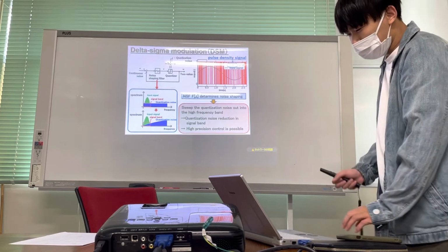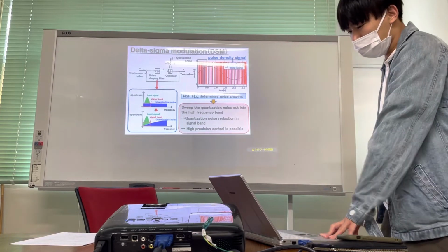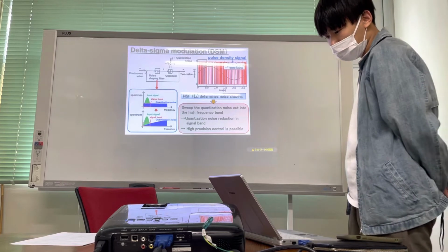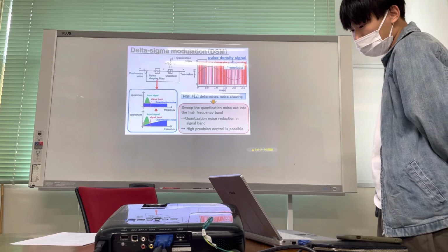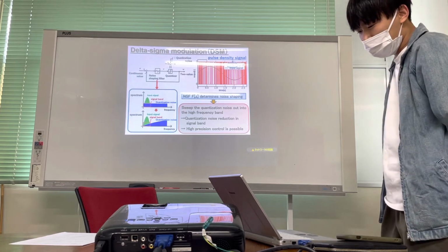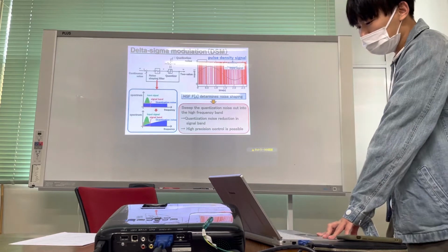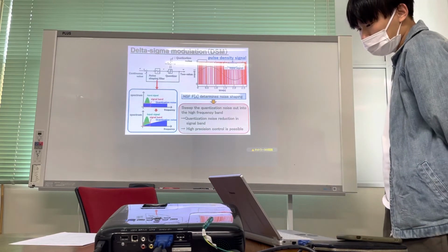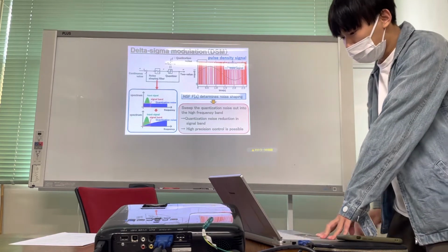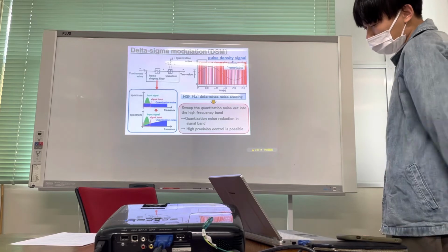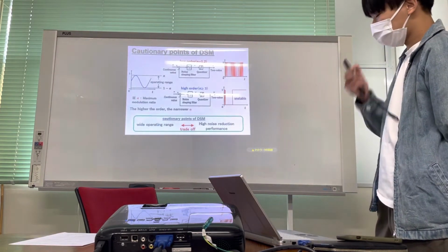The figure shows the delta sigma modulator used in this work, and this noise shaping filter determines how the noise is shaped. We designed a noise shaping filter to reduce low frequency quantization noise, which is the frequency band of the plant. However, it is not just a matter of designing the filter to increase the noise reduction performance.